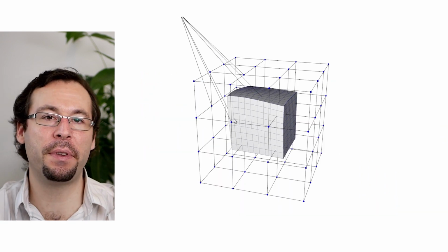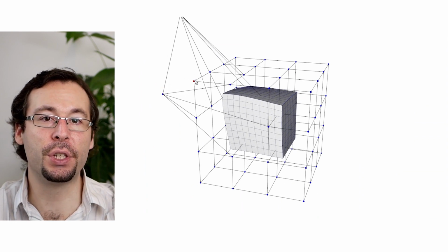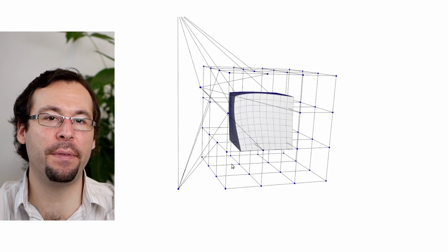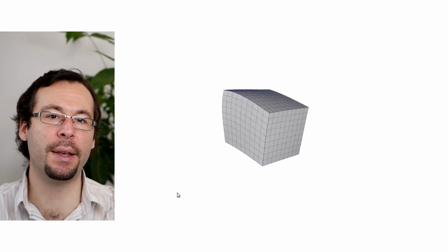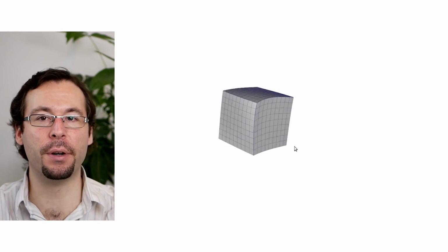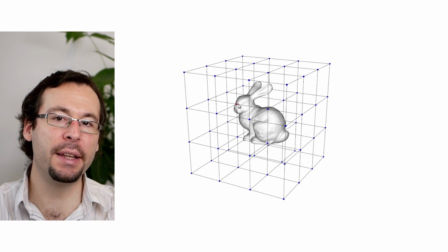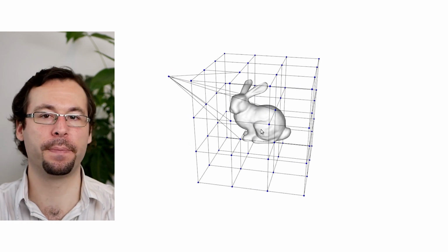And you can see the type of deformation applied to the shape when the grid is modified. Using smooth approximating polynomials ensures that your final deformation remains smooth as well. And of course, we show the case where B are the Bernstein polynomials in the case of the Bézier function, but you can take any basis function instead, such as B-splines or NURBS.